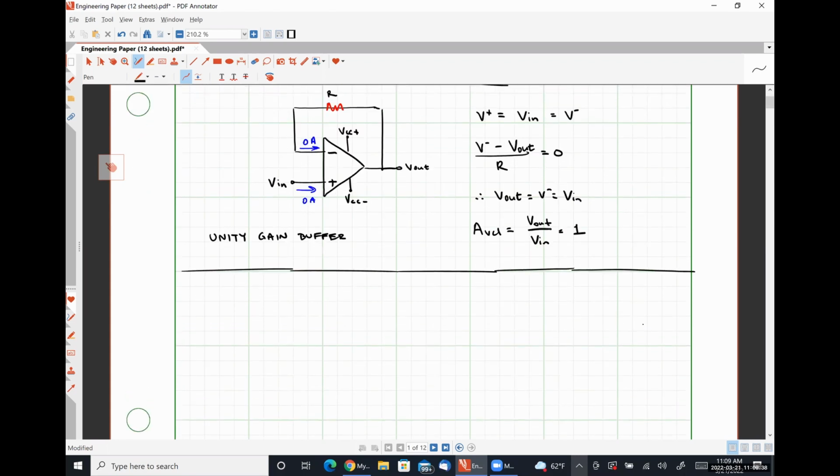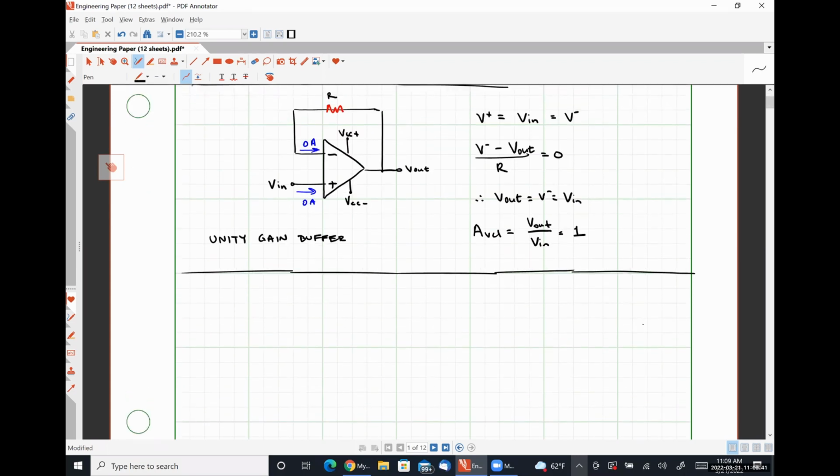The next circuit that we are going to analyze is going to look very similar. And in truth, the unity gain buffer amplifier is actually a specialized case of this guy. We are again going to apply our input signal directly to the non-inverting input node.